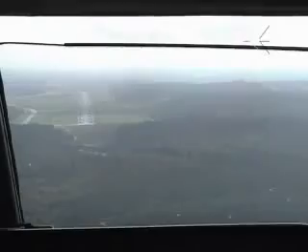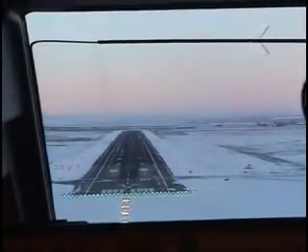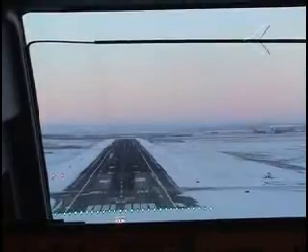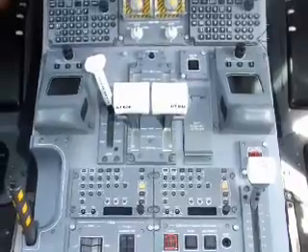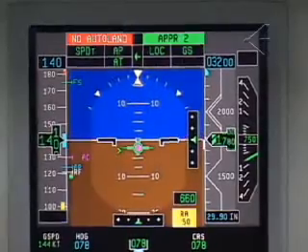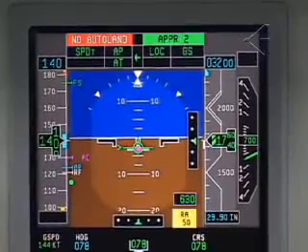The Autoland system available on the Embraer jets allows operations with decision heights not less than 50 feet height above touchdown zone and runway visual range not less than 700 feet, Cat 3A, or 600 feet for Cat 3B. Autoland certification also requires compliance with Cat 2 requirements for the portion of the approach prior to 100 feet height above touchdown zone. The system is certified in the fail-passive classification, that is, in the event of a failure there is no significant out-of-trim condition or deviation of flight path or attitude.